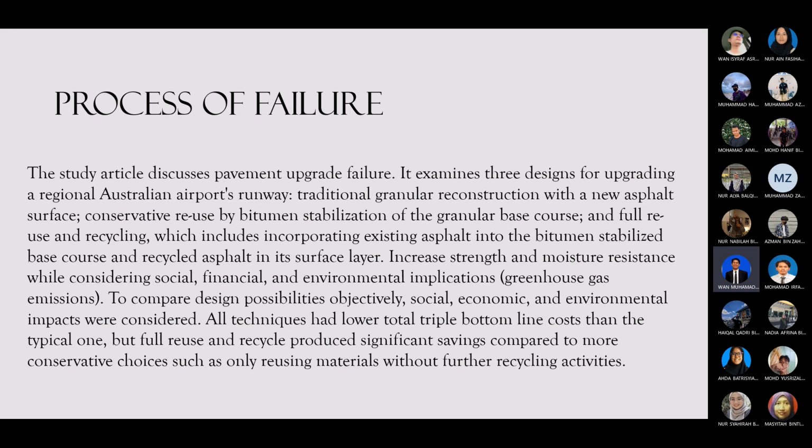Second is conservative reuse by bitumen stabilization of a granular base course. And last is full reuse and recycling, which includes incorporating existing asphalt into the bitumen stabilized base course and recycled asphalt in its surface layer.